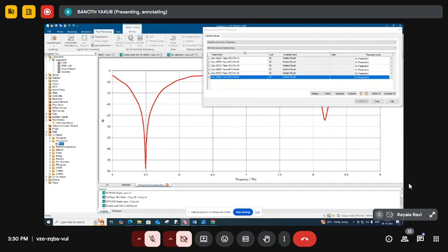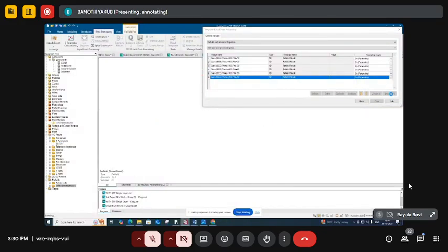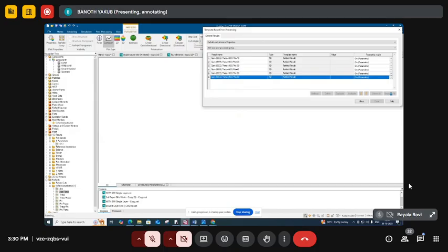These phase angles we have changed. After that we can see whether we get results up to 60 degrees, whether in this axial ratio and return loss bands we are matching the axial ratio below 3 dB or not. After that, with the given phase angles, just click on evaluate all, and it will be evaluated for the given theta and phase angles.